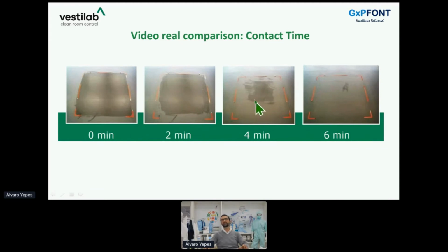Certainly not, because here probably more than 50% of the surface is dried. And that's what you need to be doing in practical terms: verifying with a rationale the real time your surface remains wet in your facility, with your ventilation, with the tools that you use to apply the liquid.